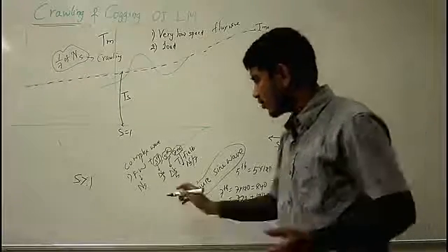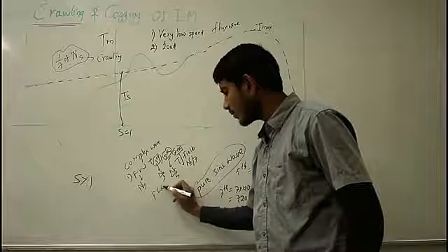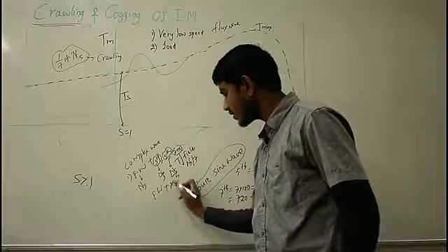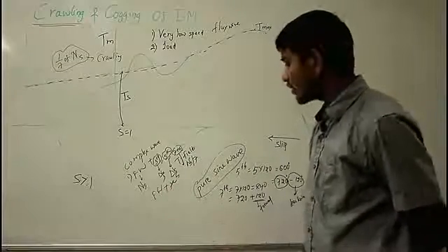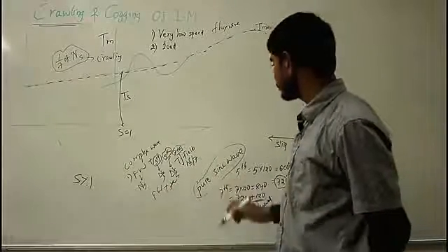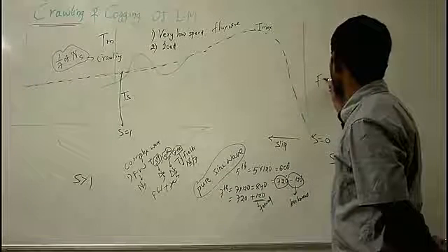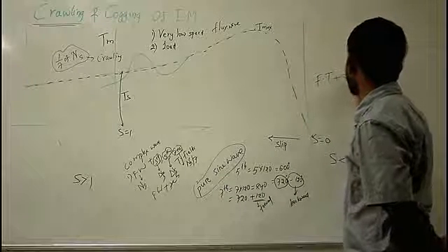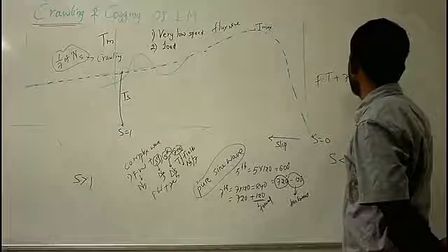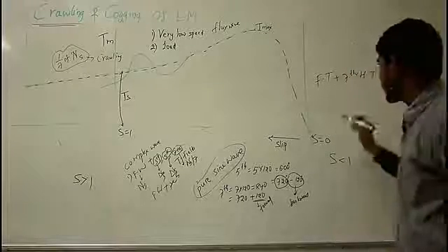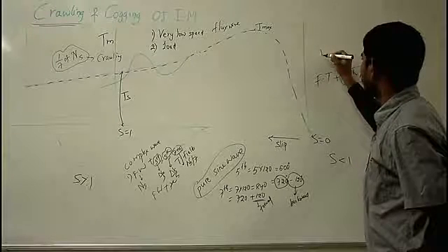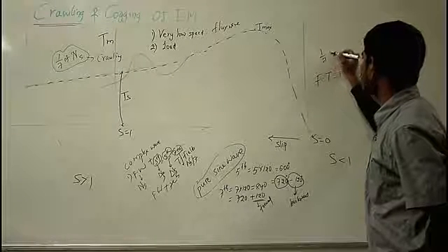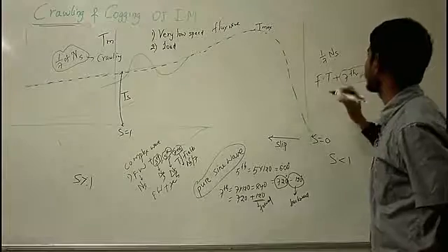That means now we are left with the fundamental wave plus the 7th harmonic. The resultant torque developed by your motor will be equal to the fundamental torque plus the 7th harmonic torque. The 7th harmonic torque reaches its maximum positive value at high slip with a speed of 1/7 of Ns.